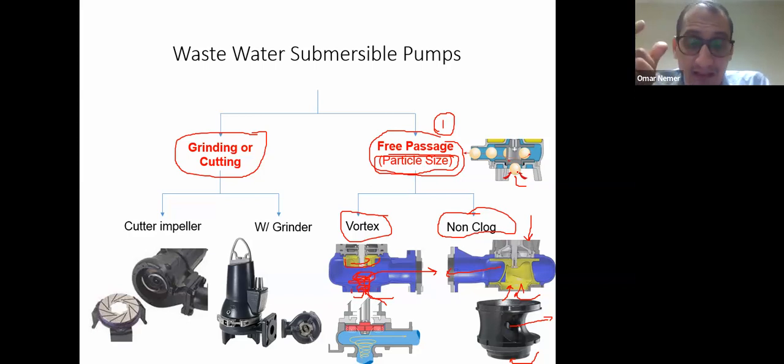If it's bigger than that, the pump cannot suck it and deliver it. So particle size of 50 millimeters means these solids which come with the water, if they have a dimension of 5 centimeters, can be pumped, but not more than that.